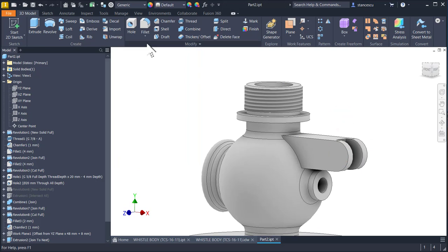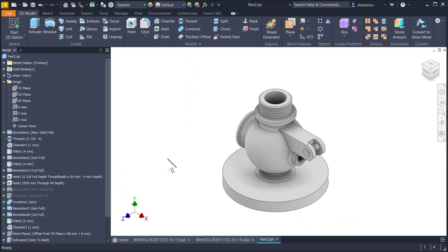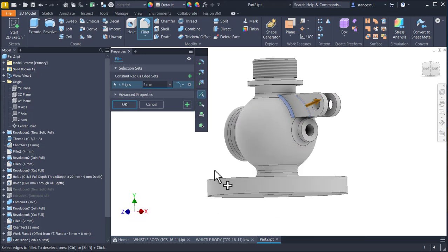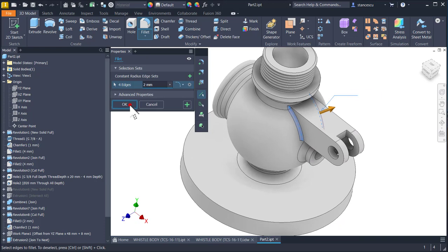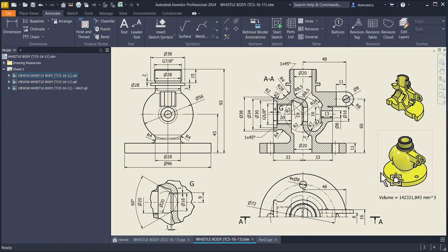now we have to place that hole of 8 millimeters on this face with this center through 8. Okay, good. Another fillet of 2 millimeters is here and also here, as in the drawing. The last things to do is to place these 4 holes, diameter of 8 on a circle of 72.